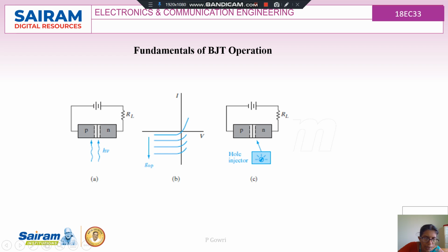When the diode is reverse biased, we know that a depletion region is formed. The depletion region is nothing but the junction of our P and N regions. So in reverse biased condition, a diode will be having a very small amount of current, which is called a reverse saturation current. The reverse saturation current will be of the order of microamperes and it will be constant for the reverse bias. The VI characteristics curve here in the third quadrant represents my reverse current.